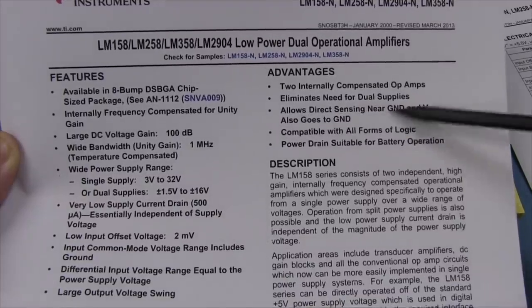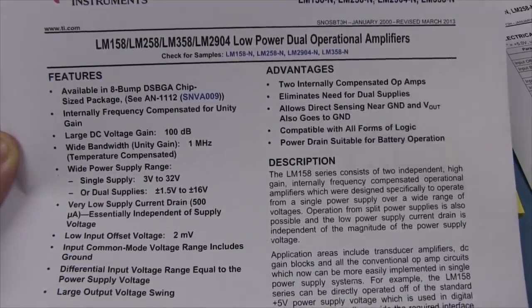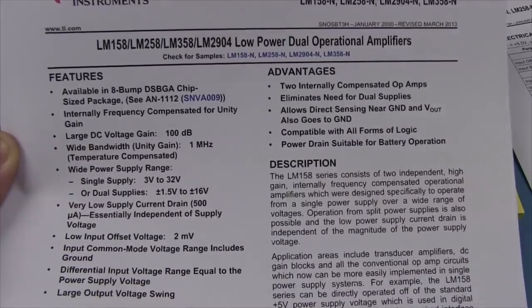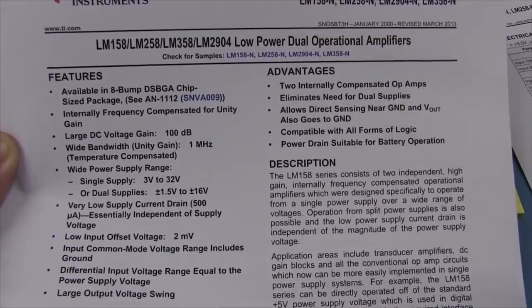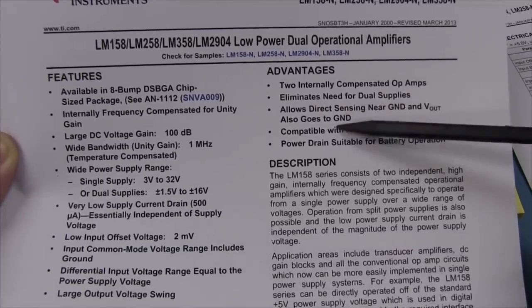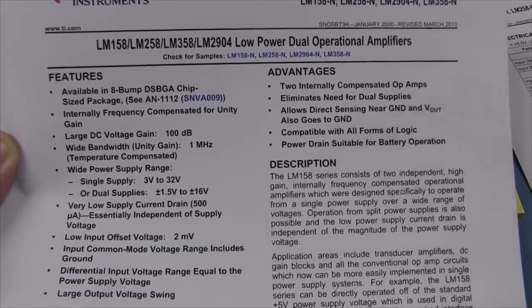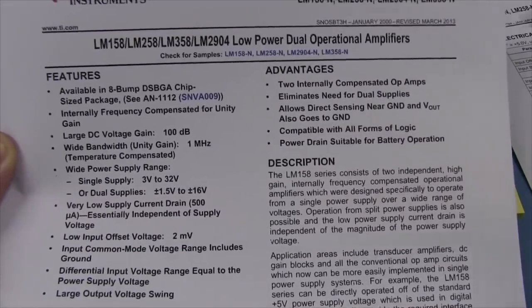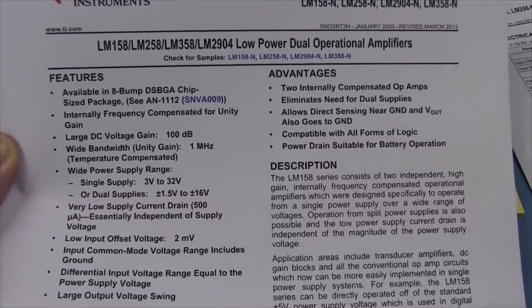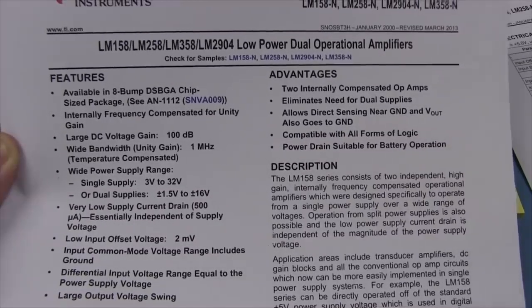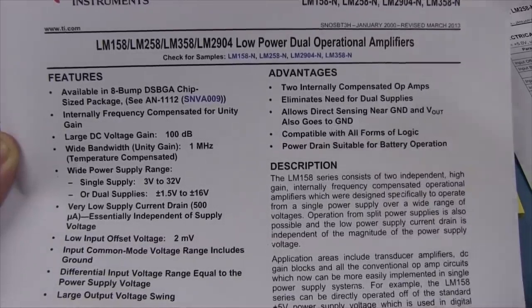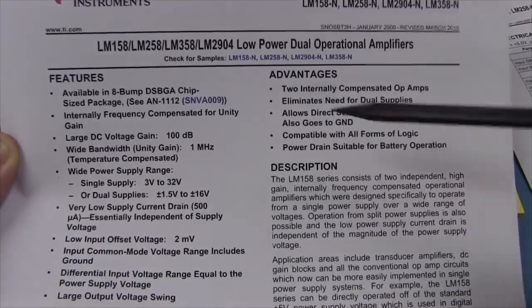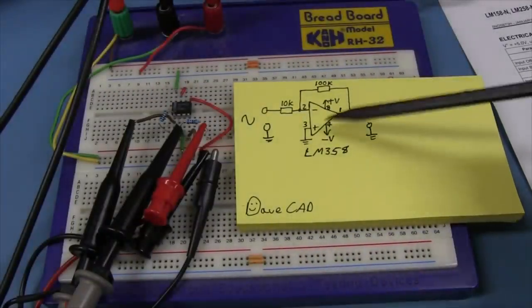So, and V out also goes to ground. So effectively, it's not rail to rail. It won't go up all the way to the positive rail on the input and output, but it will go down to ground or the negative, or well, because an op amp doesn't have a ground pin, it's the negative rail. So even if we power it from split supplies, plus minus 15 like we are now, it'll still go down to that minus 15 volt pin, or that pin 4. It'll go down.